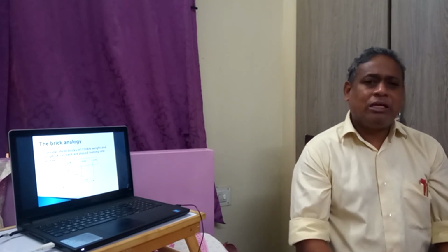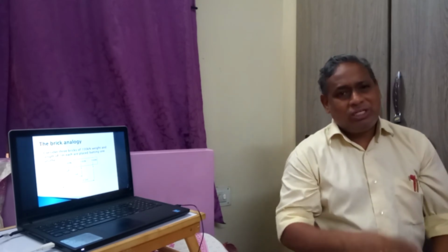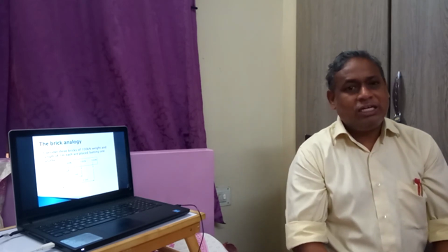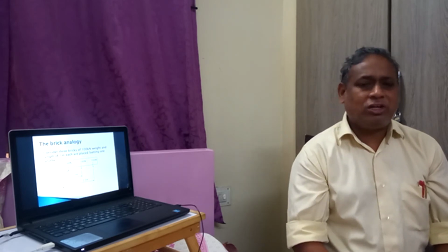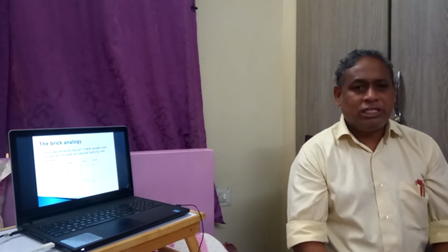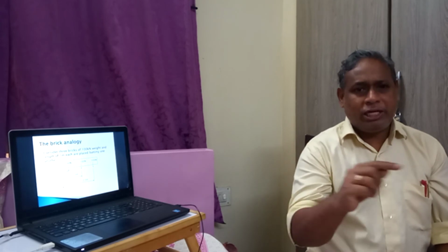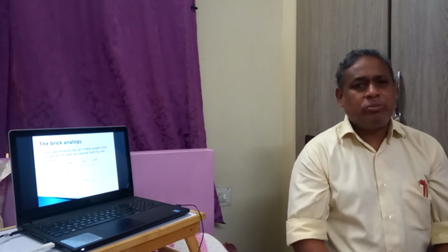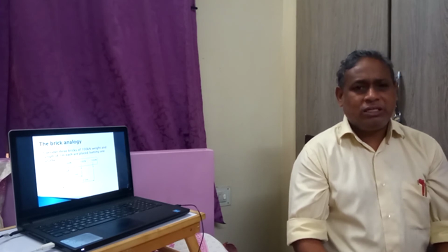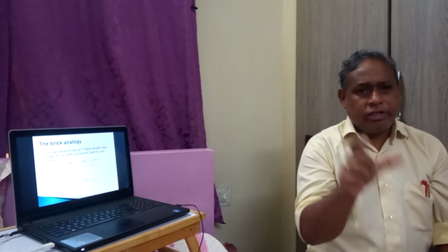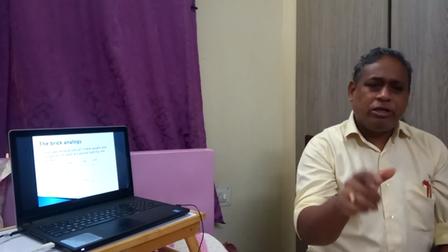We discussed that the uniformly distributed load acts through its midpoint. We have not said that it is acting through its centroid, because then the concept of centroid was not known to us. That is why we said that the entire UDL is assumed to be concentrated, as the intensity into distance, at the middle or center of the load.